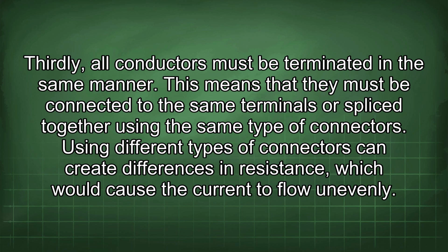Thirdly, all conductors must be terminated in the same manner. This means that they must be connected to the same terminals or spliced together using the same type of connectors. Using different types of connectors can create differences in resistance, which would cause the current to flow unevenly.